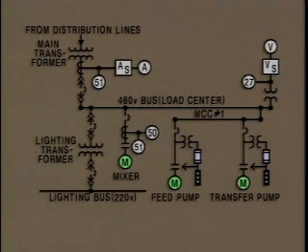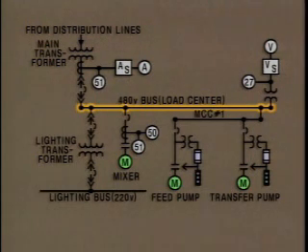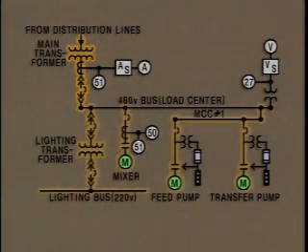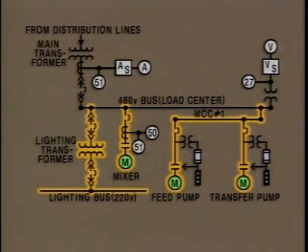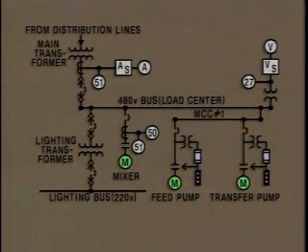The electrical system in a plant is designed to carry electric power throughout the plant. The heart of the system is the load center, or main bus. A bus is basically a conductor that connects a power source to several load circuits. Load circuits supply individual loads with power from the load center. A load can be a device such as a motor that uses power, or a device like a transformer or a motor control center that supplies power to other circuits.